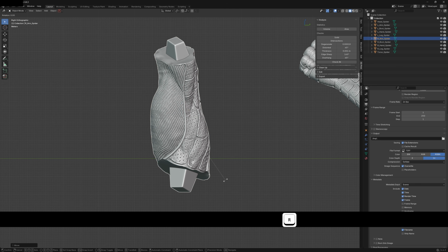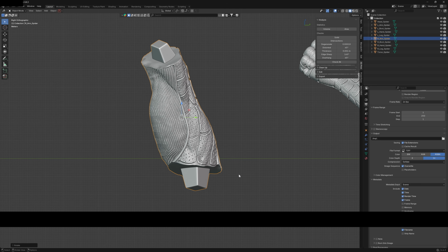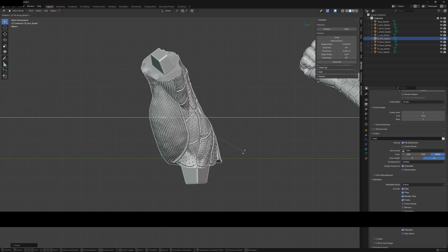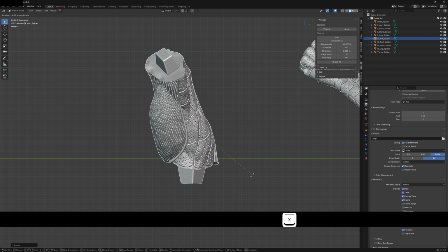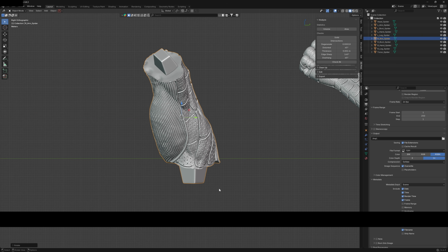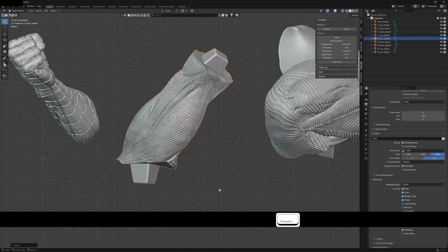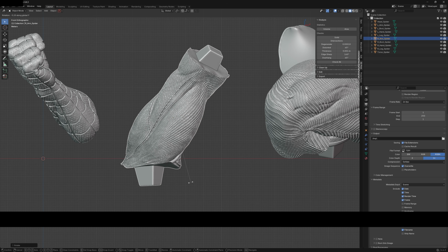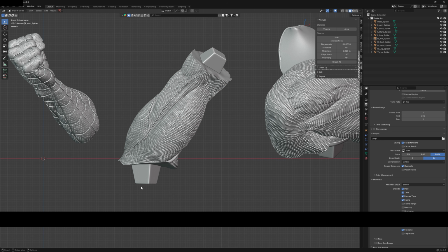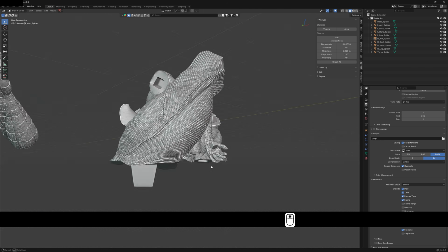So I want to see if rotate X or rotate Y just to get that, and then rotate X again to get that flat. And then I press 3, by the way, to go to the right hand side view, 1 to go to the front. So slightly not aligned at the bottom, so rotate Y, so R, Y. Right, if that was the contact point, this is obviously grow up here, so just got to check.